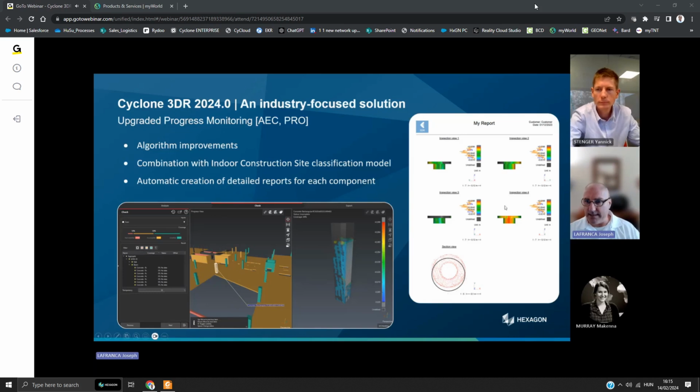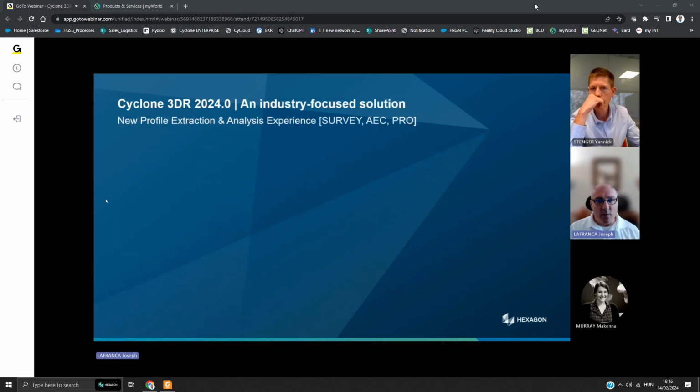And on the right, we've just got some shapes of some giant, very big flanges that were scanned and overlaid to the model to see what the deviation report was. And the color is just a heat map, right? The more red something is, the more out of tolerance it came. Of course, you get the numerical reports, but the heat map gives you a quick view of where our hot spots are.